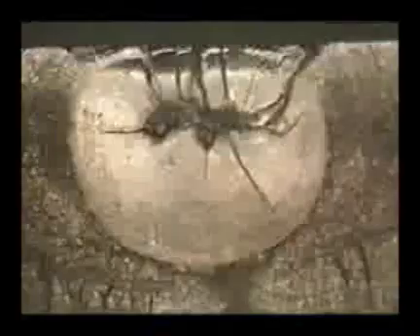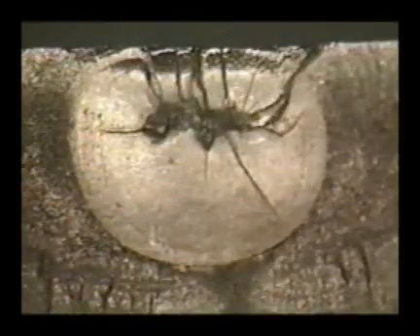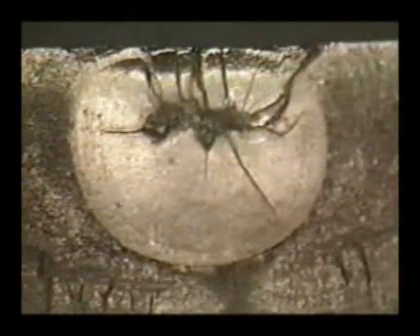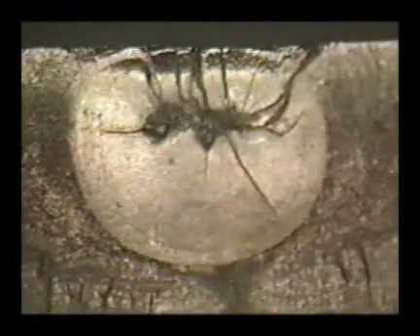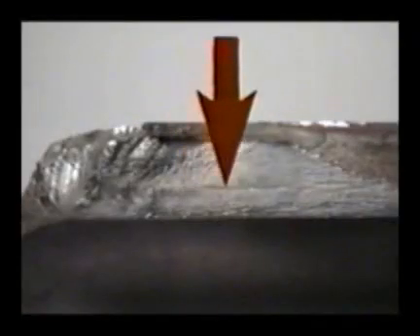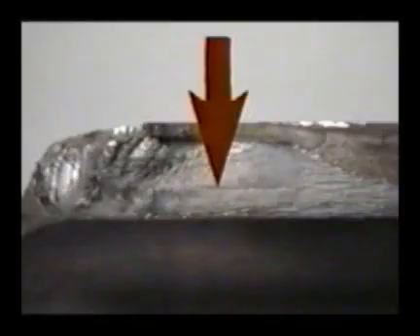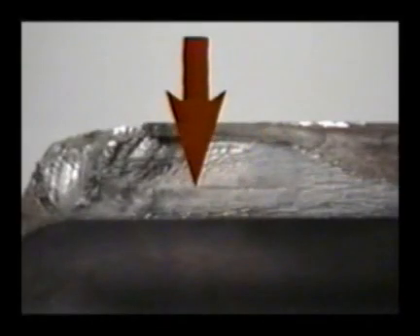If a crack starts from a spherical inclusion or across a long, thin inclusion, it can produce a bullseye appearance. The crack grows very slowly away from the inclusion, creating a target-like appearance with the inclusion at the bullseye. If cracking starts along an inclusion's length, instead of a bullseye, we'll see a normal fatigue appearance.